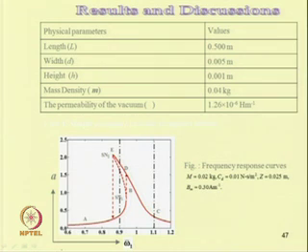Also, one can study the response of the system, what we observed in the beginning. From the response curve, one can see the jump up, jump down phenomena. These points are saddle node bifurcation points. For different system parameters one can observe different phenomena in the system.